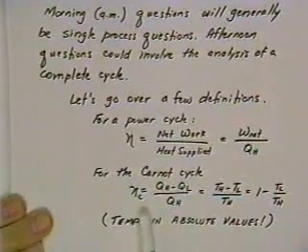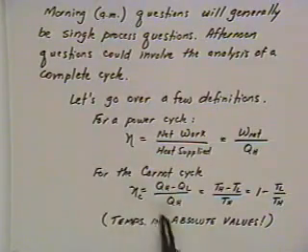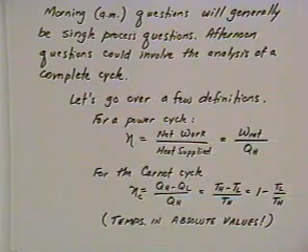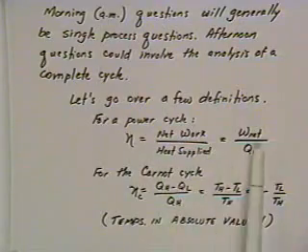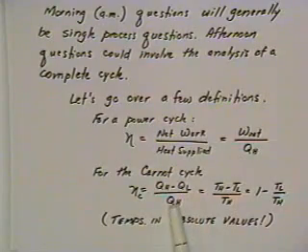Now, for our old friend, the Carnot cycle, which also applies to any reversible cycles as long as they are fully reversible, the efficiency is generally said to be the highest efficiency that you can encounter, as it would be for any reversible engine. It is QH minus QL over QH. The net work is defined as QH minus QL, and heat input is QH.